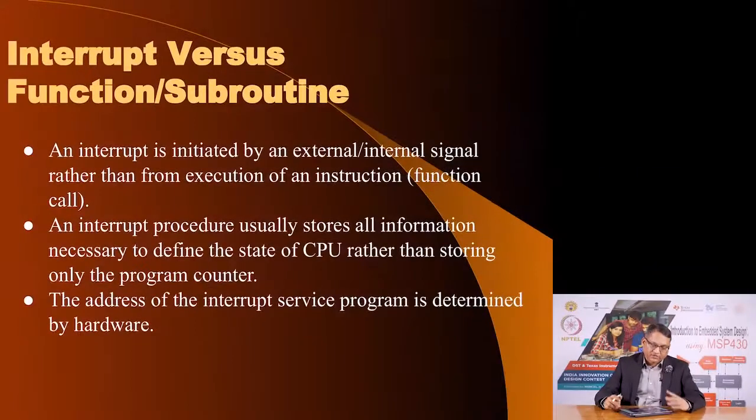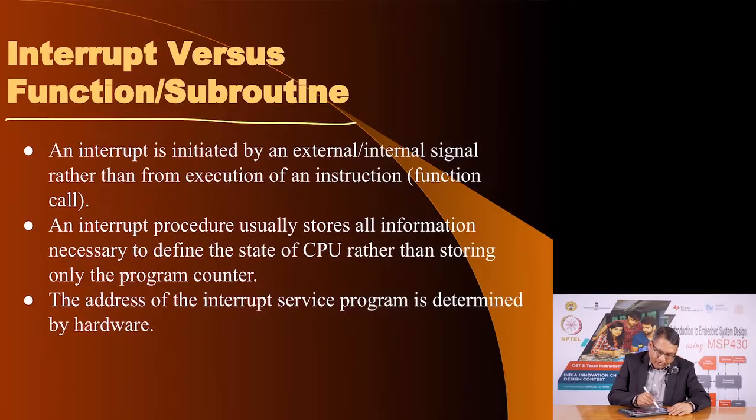Now, how do you handle interrupts? As I mentioned, your main program would be suspended and you would execute a subroutine, and therefore, it may appear that responding to an interrupt is like executing a subroutine. Indeed, it is, but it is different from a conventional function or subroutine, for various reasons.